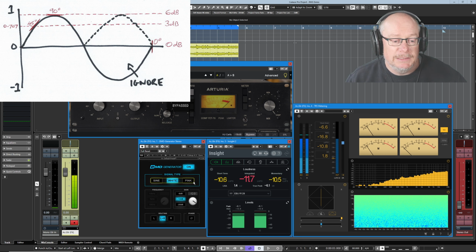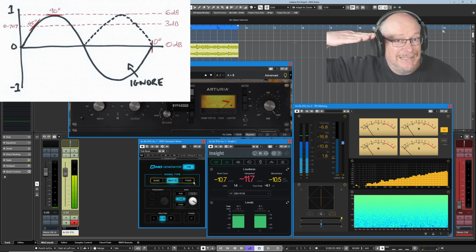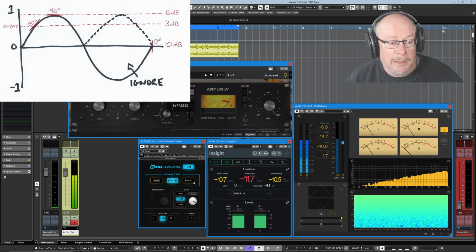So all of this means it's unbelievably difficult to even get to any kind of baseline. Are you supposed to use sine waves? Are you supposed to use white noise? White noise is better than pink noise, by the way, because it's more consistent. It's more in terms of amplitude. You get a more regular signal out of it.